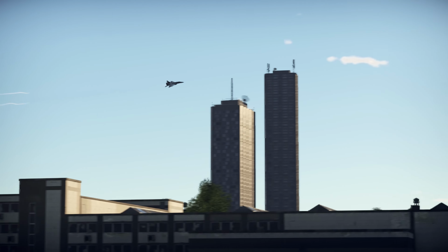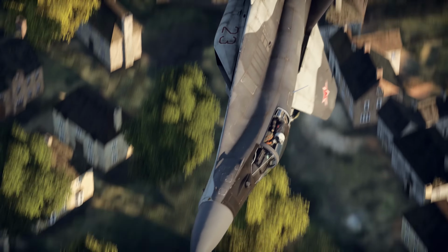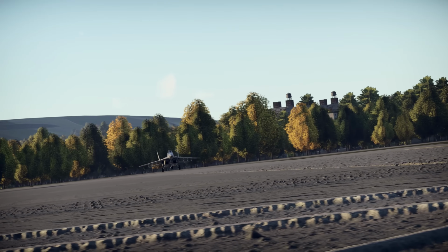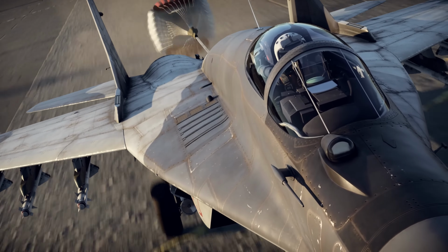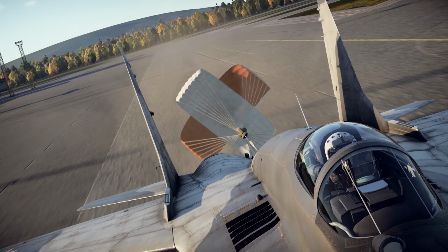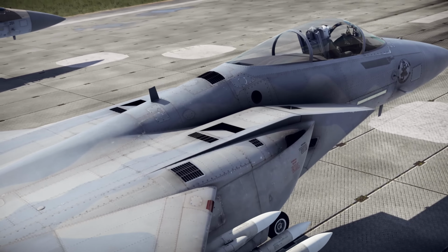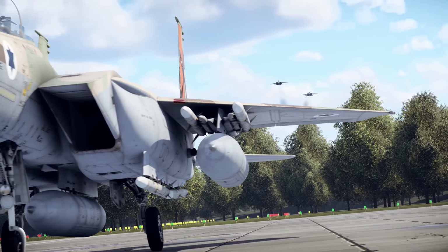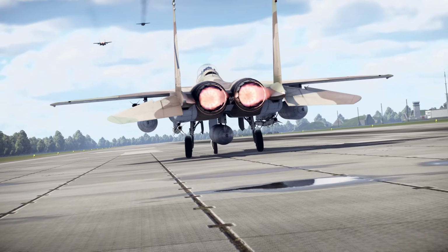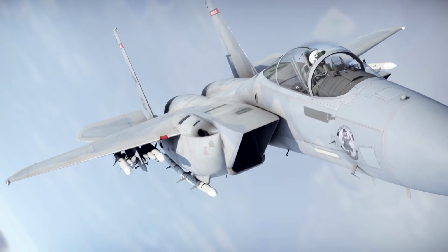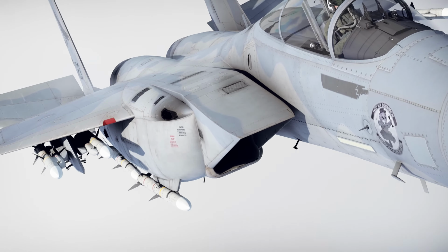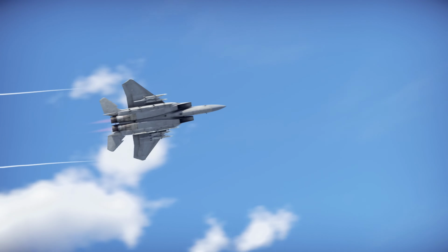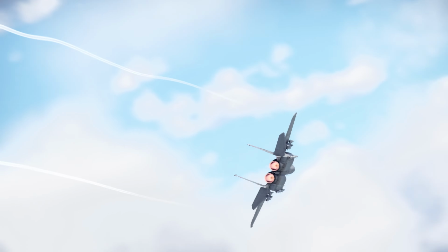It's lower because energy is lost to airflow distortion, accessory drives, intake inefficiencies, and aerodynamic losses. It also varies with speed, altitude, temperature, and even intake design. On some jets, engineers actively optimize the intake. For example, the F-15's inlet moves depending on angle of attack. As a result, the same engine can behave very differently on different aircraft. In the game, we model the installed thrust, not the static stand value.